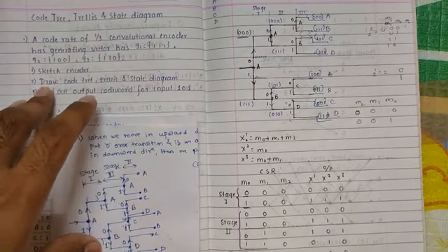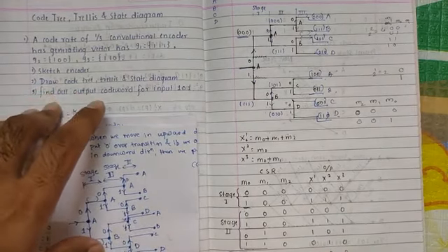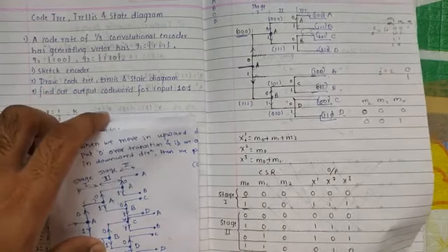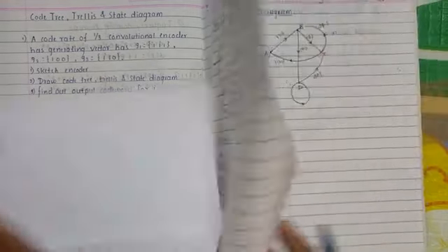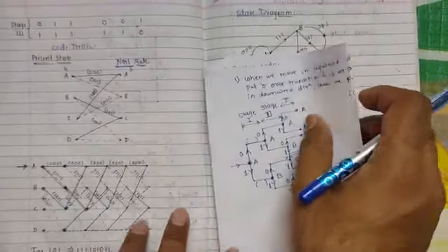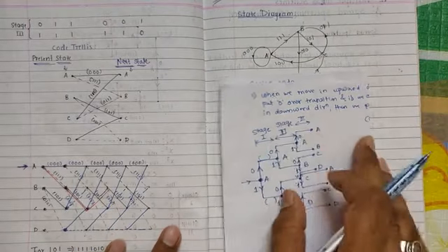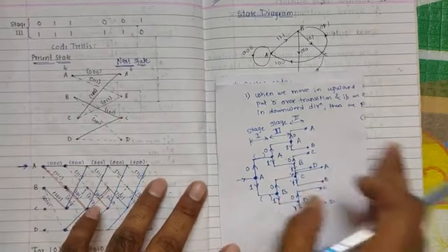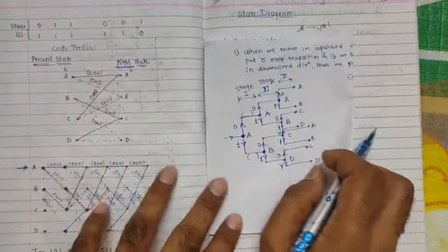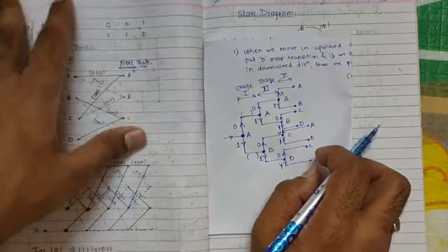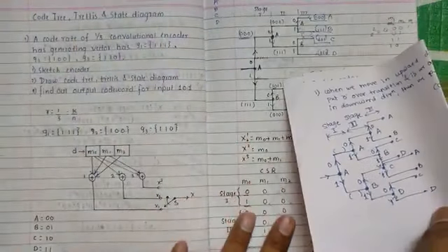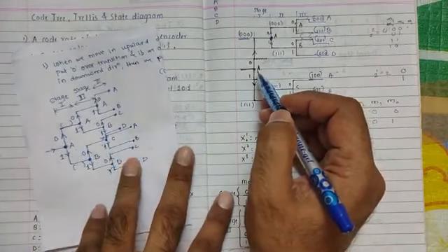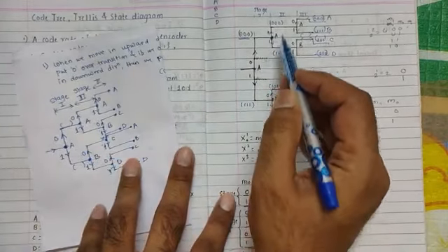Now let us move ahead and let's see how to draw the code trellis. So while drawing the code trellis, we will have to look at one simple rule, and the rule is like, if the input is 0, then we can draw a solid line, and if the input is 1, then we can draw a dotted line. Now from the code tree, one thing is for sure, if we are at input A, it will only give us two output nodes, that is A to AB.